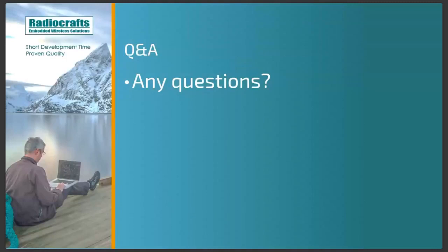Frequency hopping is a question from Stefan. Frequency hopping in itself doesn't affect range. However, you do get an advantage versus noise and fading, because the variation of the signal over time will be different for different frequencies.